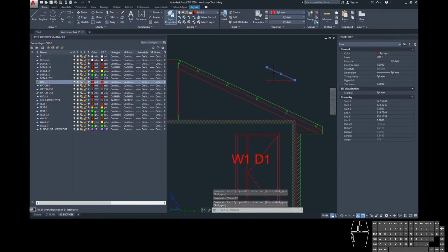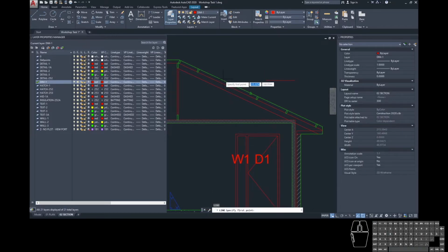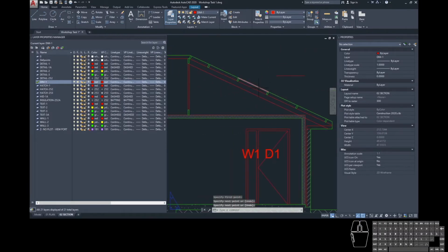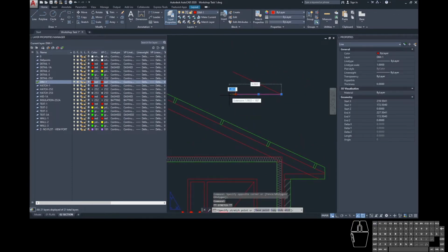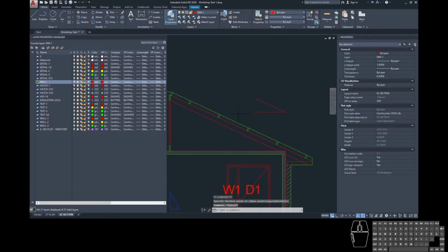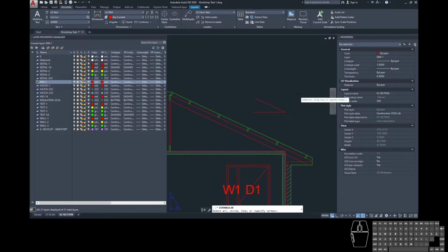The other way that we could do that to make sure that we're being really accurate with that dimension is to actually draw a line that is matching upon that roof, and then we can move that line out to here. That's going to help if we don't actually know the angle at which our roof is sitting. We will have to create a line that will match. And then we can come back to our Annotate tab and our angular dimension, and we can pop that in here.